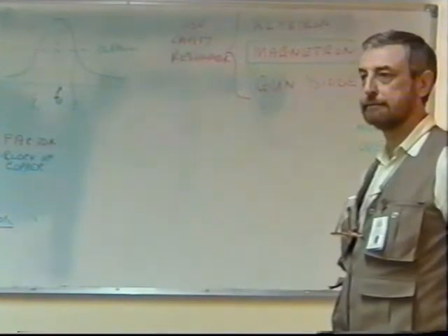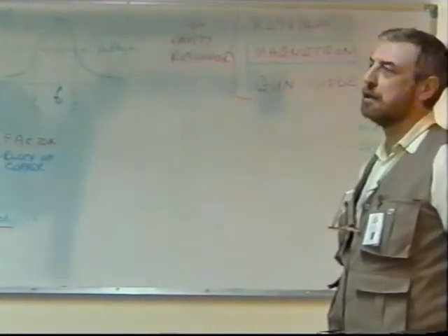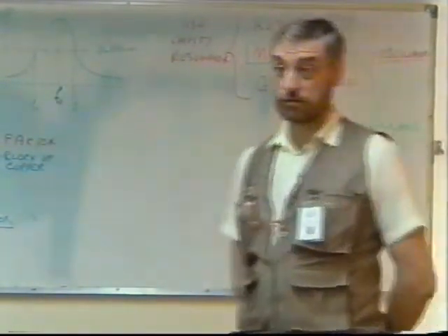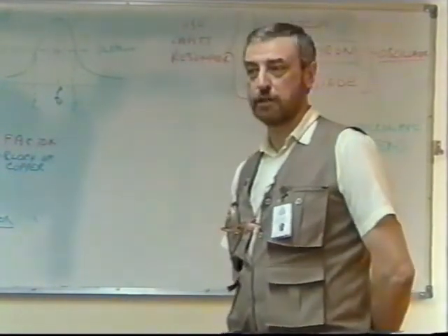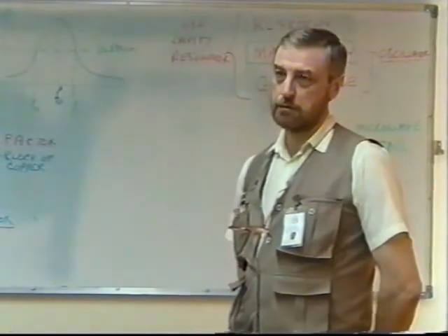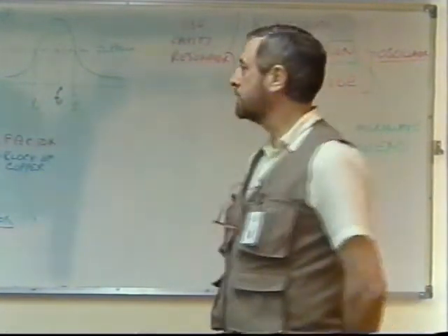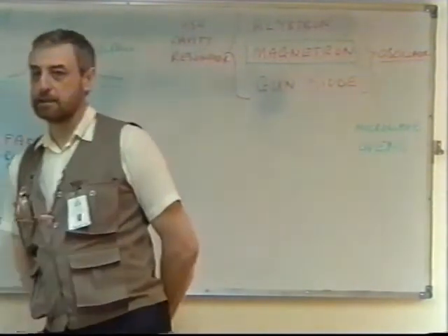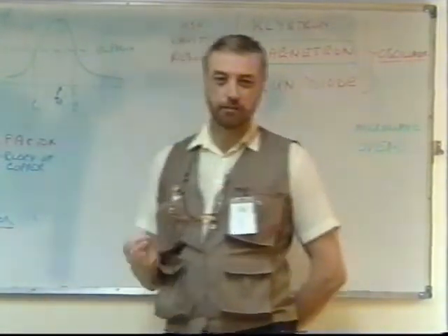So is the microwave frequency fixed or can you change it? That's an interesting point. Usually they're fixed. Well, yes. Certainly in our applications that we've spoken about, that is point-to-point microwave links, it's fixed. We don't have any control over that frequency. You can't tune them, in other words. You know, this idea of, like we mentioned here, about changing the value of L. Can't change it. You can't usually change these because it depends on the way they're manufactured, you see. There's not much there you can change.